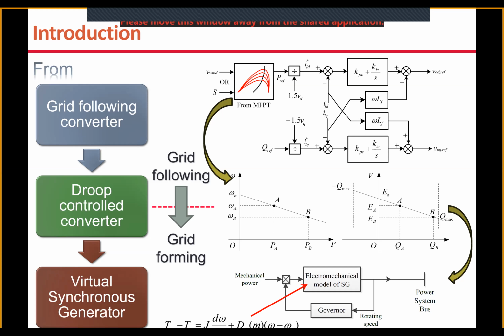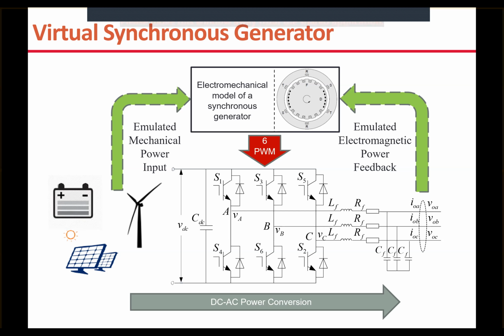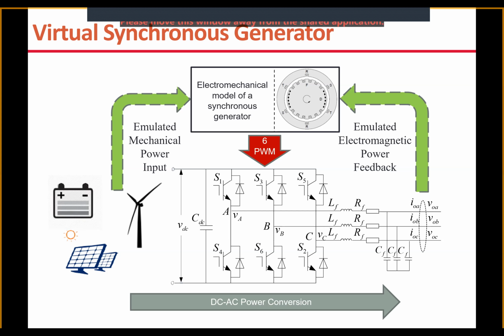And this picture shows the virtual synchronous generator control idea. This part is a mathematical model of the synchronous generator, like the swing equation, the electromechanical model.